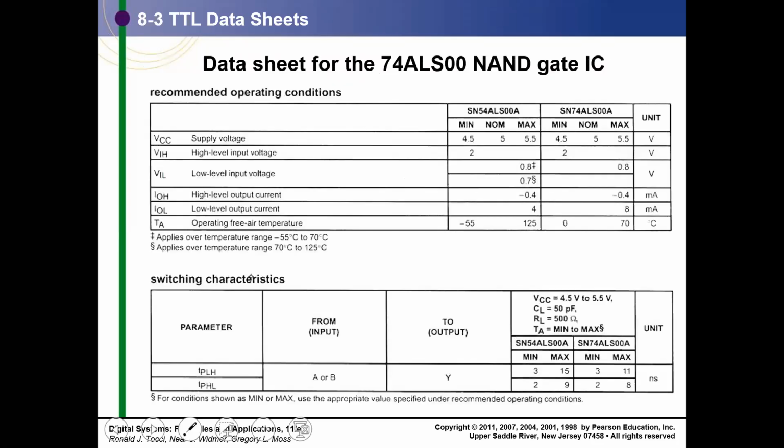This is a kind of data sheet which you will see. It specifies a typical VCC, the nominal value which you will connect, but it has a 10% variation. The minimum can be 4.5 and the maximum it can tolerate is 5.5. And you can see VIH.